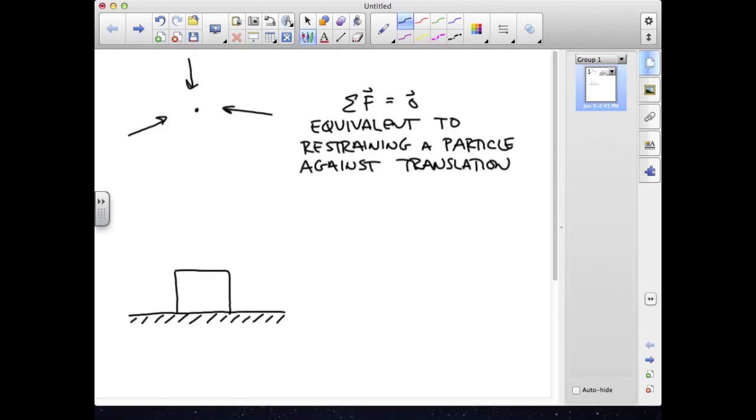From a problem-solving perspective, we're looking for the actual dimensions to be given. If dimensions are given, we'll treat it as a body, and this requires an additional set of equations beyond force equilibrium to ensure total equilibrium. If no dimensions are given, we'll interpret this as instructions to treat the object as a particle, and equilibrium will consist entirely of force equilibrium.